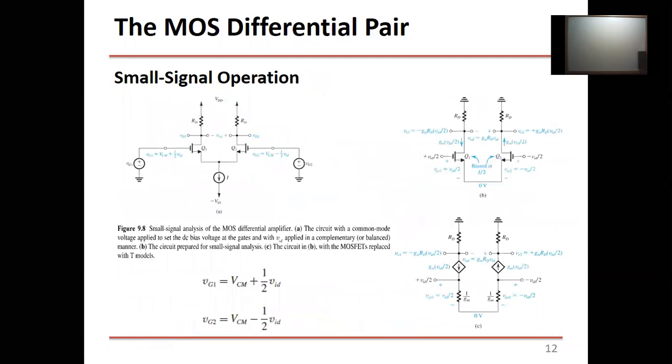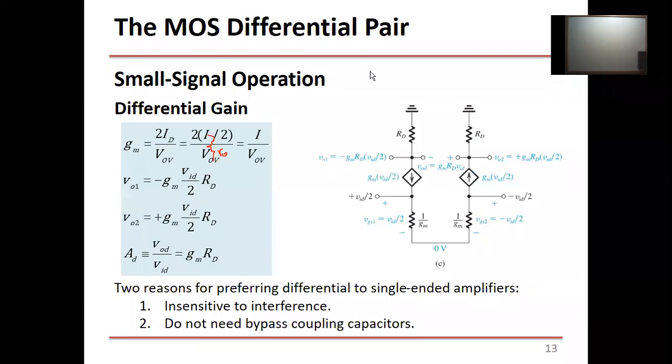Well, if you go back to the transistor here, since this is ground, in AC, this is ground. So RO is going to be here, from the drain to the source. If you go back to the AC equivalent, let me delete this. Where's RO here? RO is from this point here, all the way to the ground.